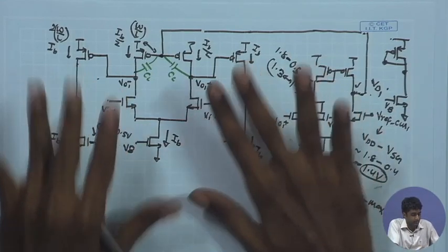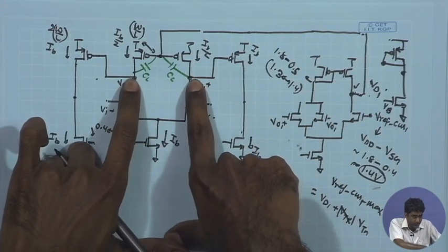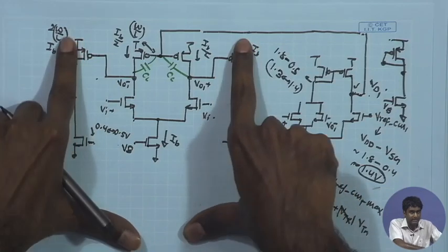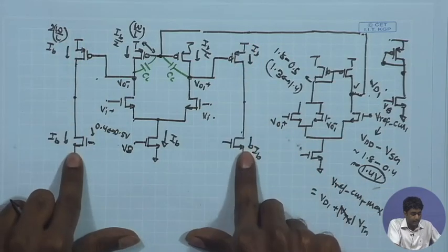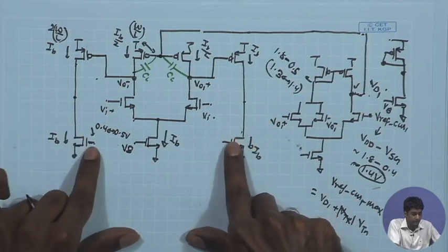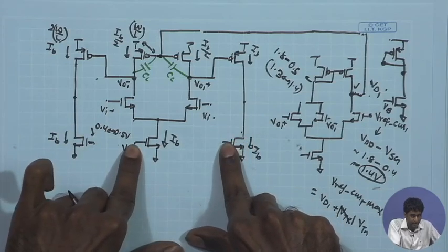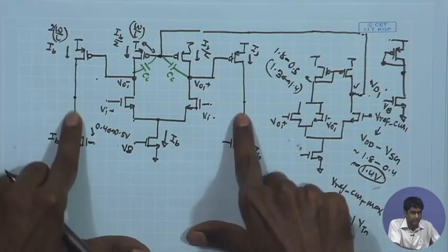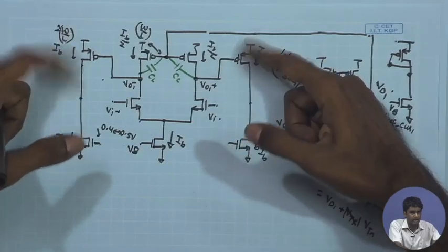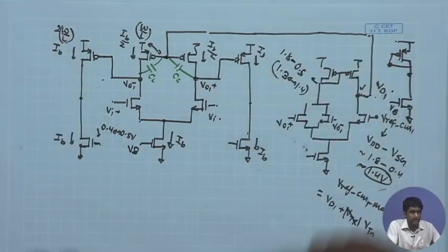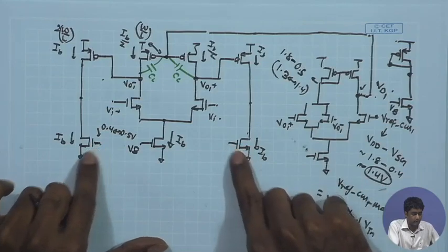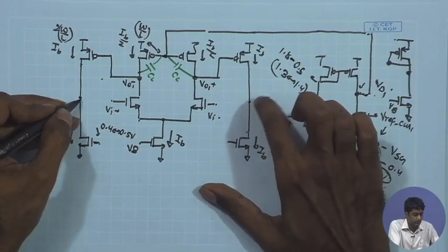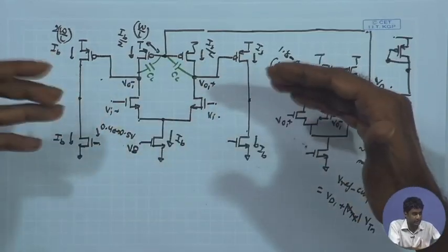So, the purpose of this is to get an appropriate DC point over here which allows the bias current IB in these two PMOS transistors, and at the bottom side we have these two NMOS transistors where the gate voltage is expected to be close to this bias point. Their dimensions are also close. As a result, we are trying to enforce IB in this NMOS also. So, we are just trying to ensure that both this PMOS as well as NMOS are biased with the help of these gate voltages to establish IB current, and then it will be more convenient to have the output voltage close to VDD by 2.